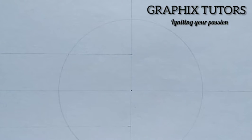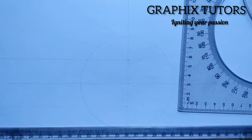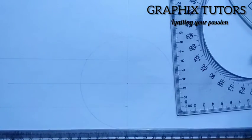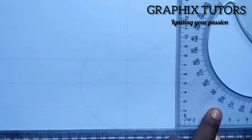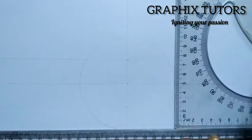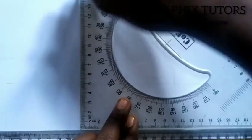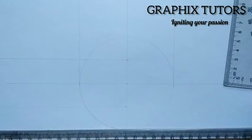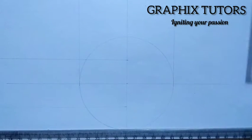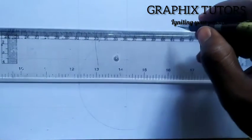So I'll move forward and I'm going to project the edge of my circle, placing my compass and T-square on the edge of my circle. I'm going to project this up. I'll come here also and project this up. You can see that. Now I'm going to join the two last ends here at any given radius away from the circle.